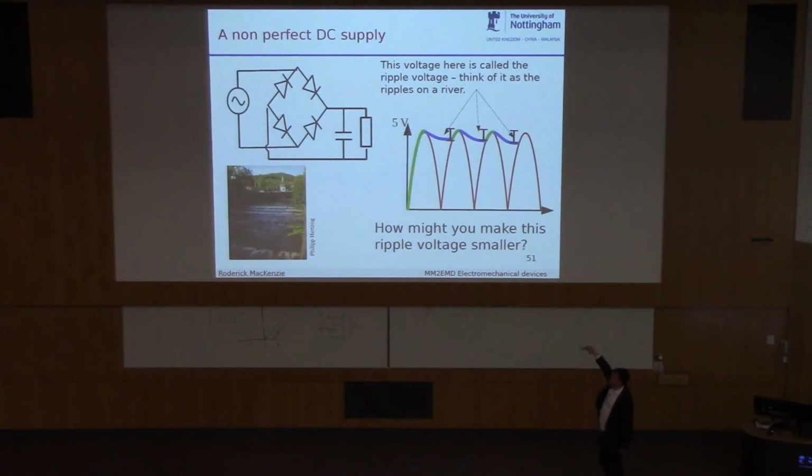And also, the mains is totally variable, so it's not always totally steady. So it's never 240 volts, absolutely bang on. It goes up and down. And also, the shape of the sine wave changes. So an ideal sine wave might look like that in my world. But if you've got lots of these power supply circuits with capacitors,